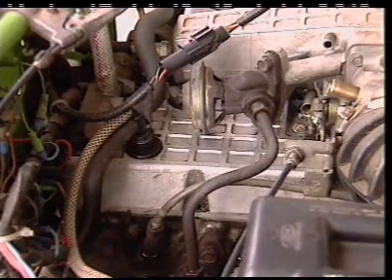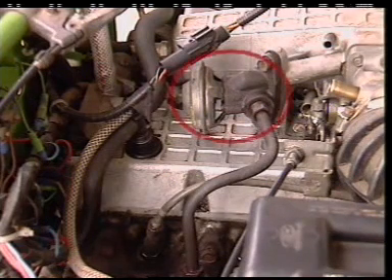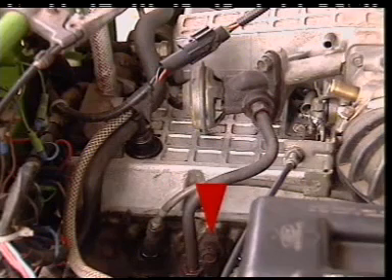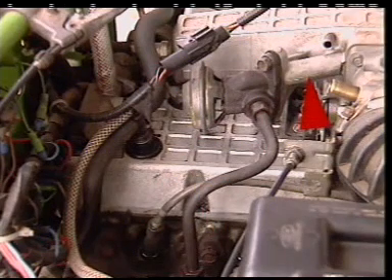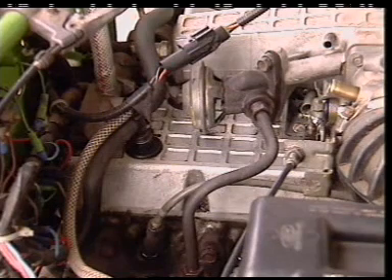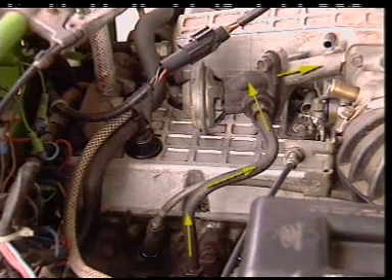If valve overlap is maintained or even increased, oxides of nitrogen can be reduced by an exhaust gas recirculation or EGR valve connected between the exhaust port or manifold and the intake system. If engine conditions are likely to produce oxides of nitrogen, the EGR valve opens, letting some gases pass from the exhaust into the intake system.